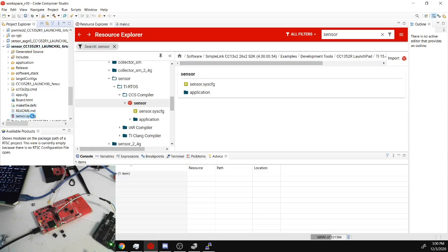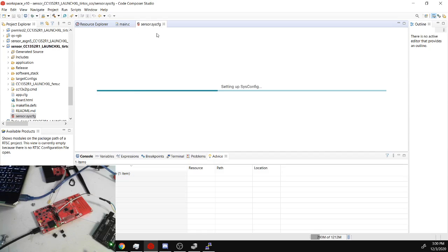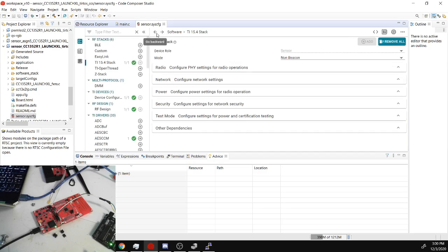If I open up this sysconfig file, you'll see that basically everything is working, but we don't have access to the LPSTK sensors. And I'll show how I got those working as well. So the collector is ready to take the LPSTK input, but the LPSTK isn't transmitting them. It's only transmitting the button clicks. This guy right here, it's only transmitting the button clicks.